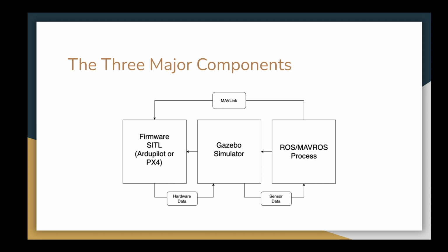Then, in the middle, there's the Gazebo simulator. The Gazebo simulator provides the physical model for the drone that the firmware on the left sees. In effect, the Gazebo simulator can have valuable sensor data. As such, you can also add depth cameras and LiDARs onto your drones and simulate that as well, in addition to basic controls by using Gazebo.